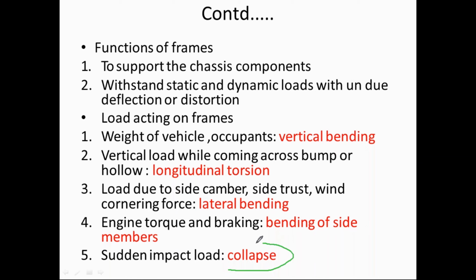Then we have a sudden impact whenever a collision takes place, so due to this sudden impact, load may be there. All these types of loads, or factors, are to be considered while designing the chassis and frames. So please remember the different basic types of loads acting: vertical bending due to load, longitudinal torsion, lateral bending, and bending of the different side members.